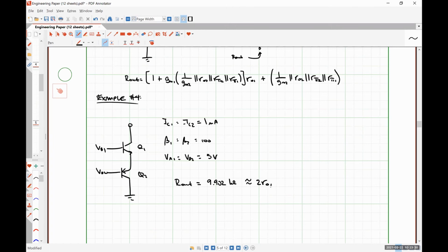Anybody got any questions or anything before we move along to MOSFETs? All right, so a very, very high level summary. We're degenerating our current sources to boost their output impedance. We have seen that degenerating with a transistor, or cascoding, boosts it to a larger value with a smaller consumed headroom. So generally speaking, it's all positives. If we cascode with the opposite type of transistor, it screws everything up, so don't do it.